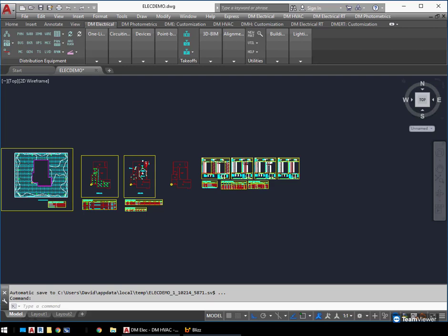Common use for this is like an apartment. In an apartment building, you might have separate panels for each apartment, and you'll have multiple apartments that look the same. And so you'll want to create one template of the panel that has the apartment all nicely laid out, and then you just want to duplicate that in the building for each of those apartments. And then when any of the apartments change, you want those changes propagated to all of the instances of those apartments that are in the project. So that's the idea behind the recurring panel, that you have a single master panel that is going to be used multiple times in a project.